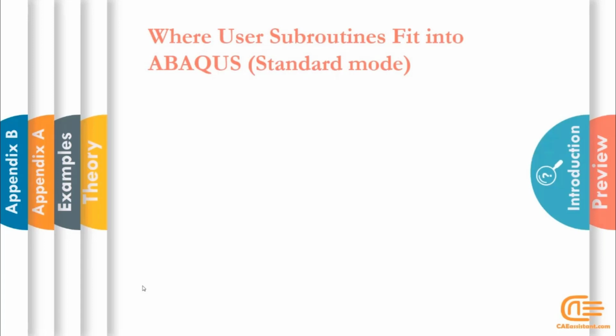Proper testing of an advanced constitutive model to simulate experimental results often requires complex finite element models, like advanced structural elements, complex loading conditions, thermomechanical loading, contact and friction conditions, or complexities like these. With these subroutines, you can define any complex model with any elastic, plastic, damage, or any other properties. It can be defined for any element in Abaqus. You can also define multiple materials in one subroutine.